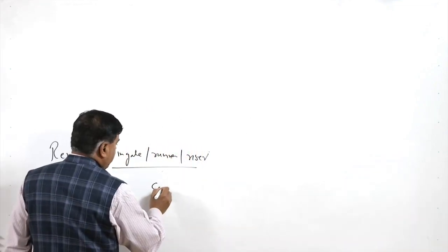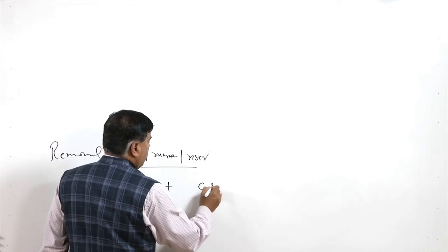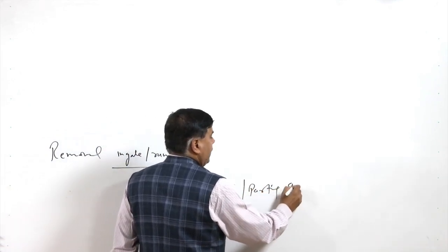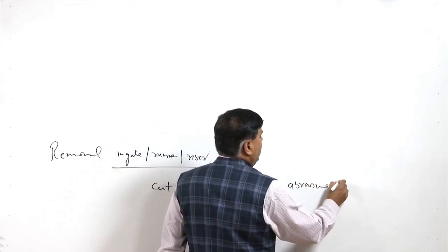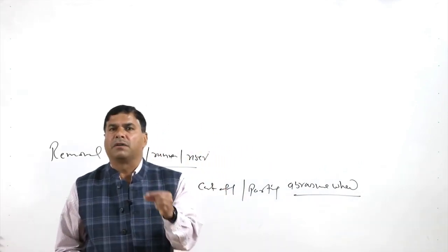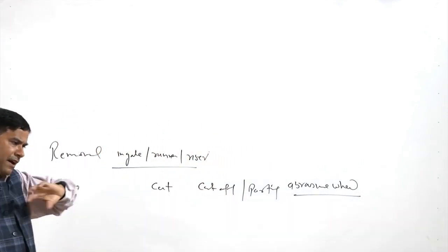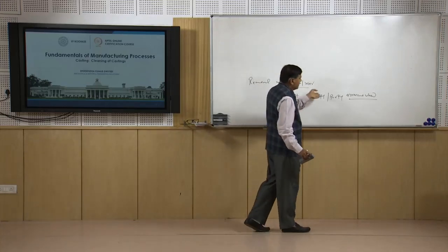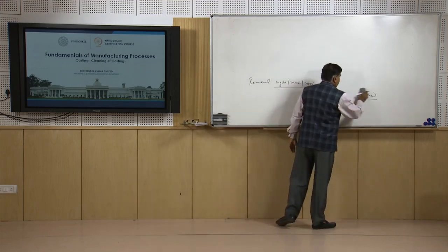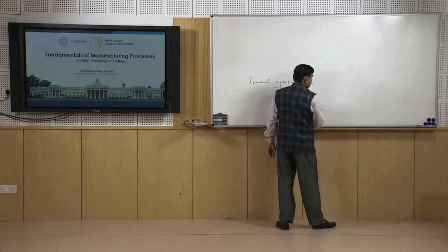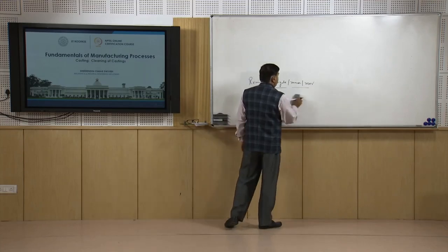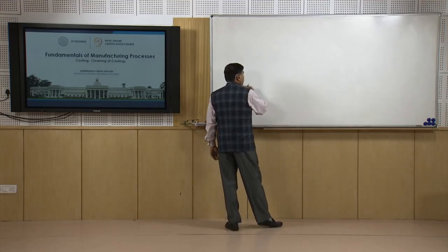Additionally, for cutting purpose like cut off or the parting, abrasive wheels are also used. These are basically the grinders which are very thin in sections, maybe 1 or 1.5 mm size. These will be rotated at high speed and the workpiece, the gates and risers to be cut, will be pressed against the abrasive wheels so that the cutting takes place. So, apart from thermal cutting and hacksaw, the abrasive cut wheels are also used for removal of these risers, runners and ingates.